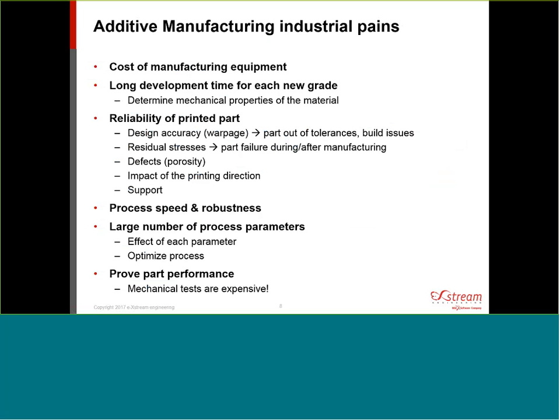So those are really high-level pains. Now, if we go more onto the shop floor and have a look at what are the day-to-day pains, we find back some that we mentioned just before. But what we see also is that there is a really big question mark on the reliability of printed parts. It's not always easy to achieve the right design accuracy because of warpage. Once you have printed your part, it is either out of tolerances, or if you have too much warpage during the build, you can have build issues that result in job abortions.